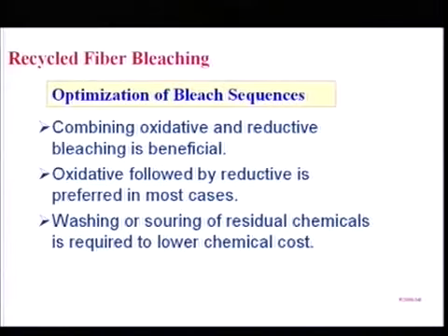Washing or neutralization step is very important. You need to quench that residual peroxide. You do not want the oxidative chemical to go and eat your reductive chemical. So, you need SO2 water for the neutralization step or a washing step to take away the residual peroxide in the system.